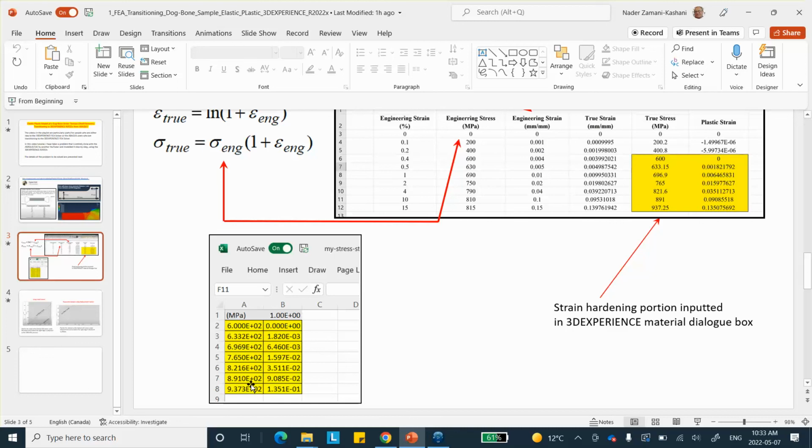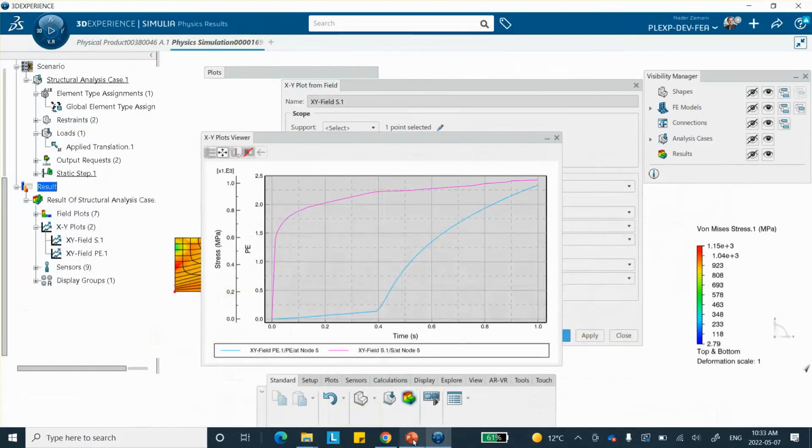So it's calculating based on that flat line, fully plastic analysis, basically, with no hardening, strain hardening, etc. So that is why when you apply displacement control, there is no issue with convergence. It converges at every increment. It's just that it generates garbage. Up to this point, I gave it data. Then this is essentially a horizontal line.